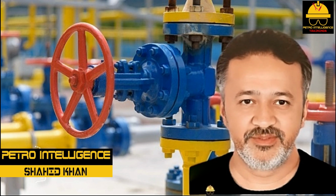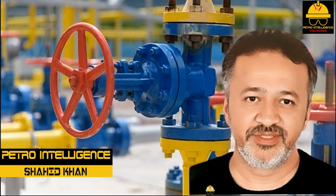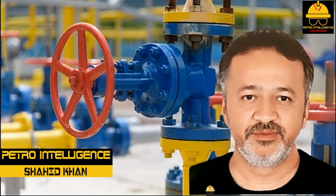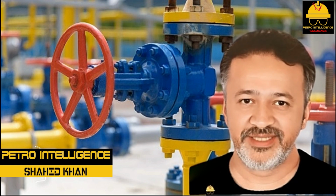Safety valves are classified by how they open and the number of adjusting rings used. Some safety valves reseat after lifting, others do not. Valves that do not reseat must be taken to the shop and mechanically reset.